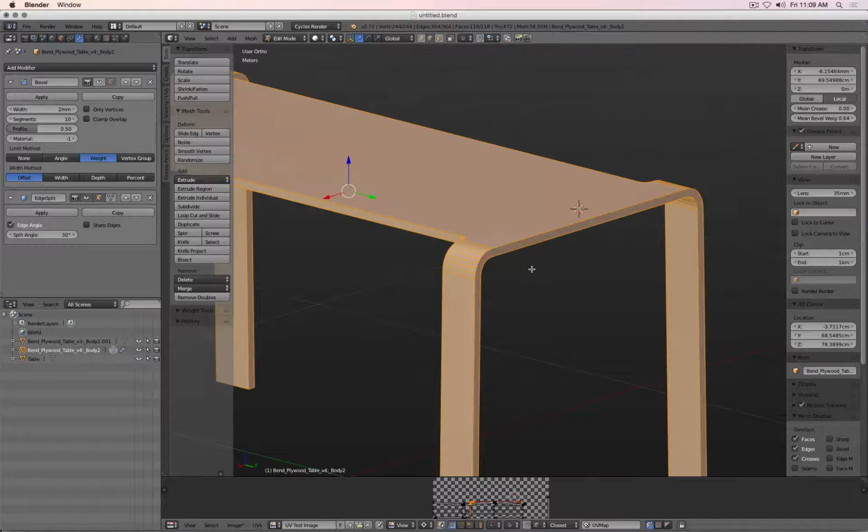So you have to, to a certain level, just accept a sacrifice or compromise. And for me, I might have to simply recreate the bevel weight, and then add a bevel modifier, which is an extra step. However, in contrast to before, you can see I have a much thinner or slimmer model. So for me, adjusting the UV mapping is much faster, more productive, more control. So this is a really easy to accept extra step to do. Because the end result is actually the same. You won't see in the rendering if there is a difference.